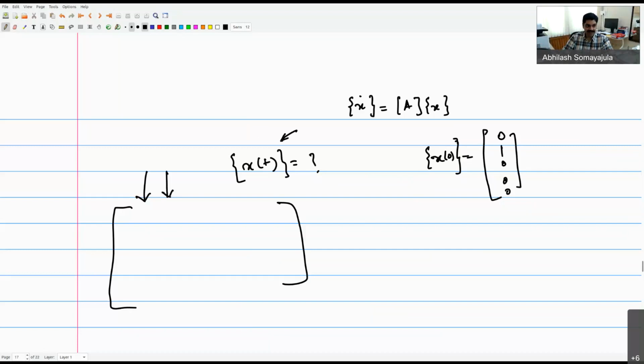Then I'll basically get n columns here, assuming that the state belongs to R^n. This matrix will be n cross n. That matrix is my U matrix. This need not be identity. In fact, it will never be identity because it evolves forward in time. Now I take this U matrix and multiply it by its inverse. That gives me the so-called state transition matrix.